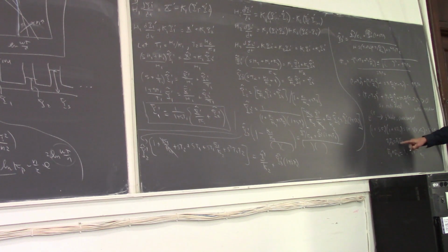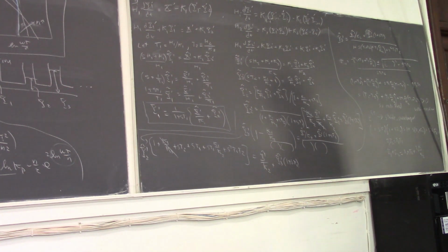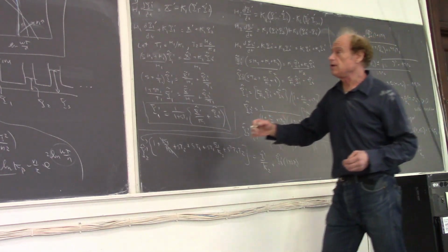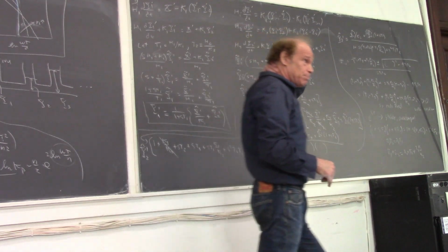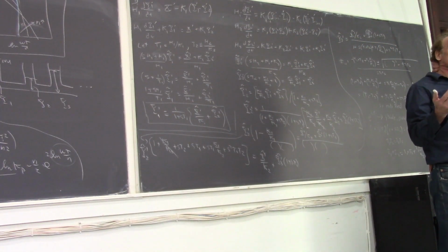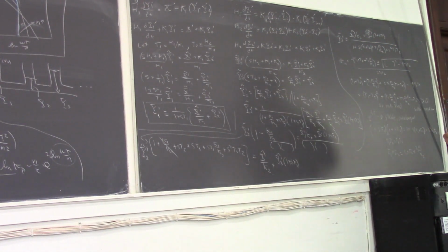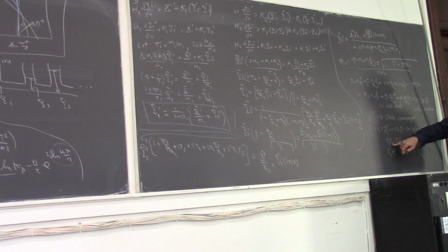That tells me that t1 and t2 are the basic time constants for each of these. They're these guys, the basic time constants. And those would be the time constants if they were non-interacting. What you can see here is the product of the roots is the same as the product of the time constants, but the sum is bigger. The sum of the sigmas is bigger.